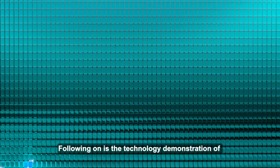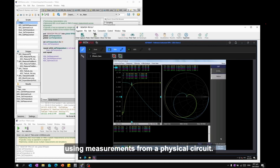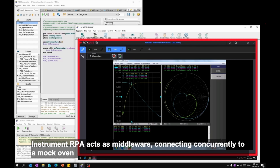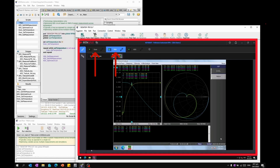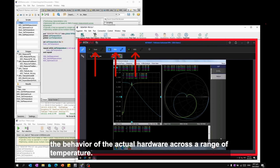Following on is the technology demonstration of optimizing a schematic across a range of temperatures using measurements from a physical circuit. On this screen, you can see two windows. The window on your right is PathWave Instrument RPA. Instrument RPA acts as middleware, connecting concurrently to a mock oven, representing a proprietary app, of which variables of interest are altered, Keysight VNA to measure the S parameters on actual hardware, and ADS software, which contains the circuitry that will be tuned to represent the behavior of the actual hardware across a range of temperature.